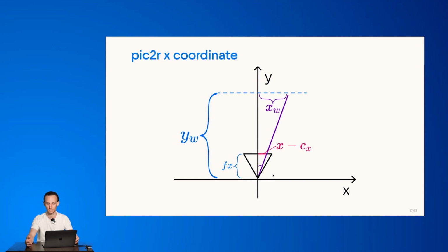For robotic football, for our league, that is enough because the balls do not really float around yet. Later, well, maybe in 10 years or something, we will have to transfer our vision to stereoscopic vision. But for now, that's not necessary, and the rest of the league is basically working with this scheme of calculating the position of the ball. We are using the scene geometry. We know in advance that the ball is on the floor, and that's why we can calculate the positions.